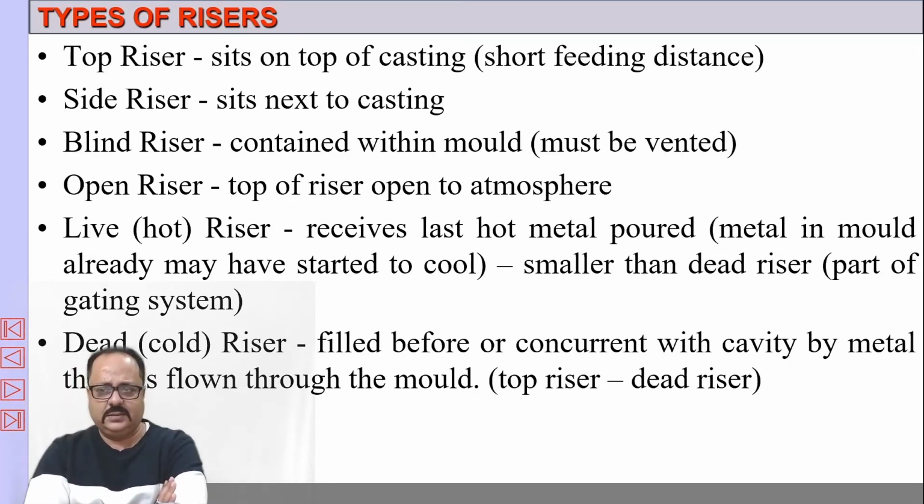Whereas a cold riser is filled before the mold cavity. So the mold cavity is filled through the cold riser. That type of riser is called a cold riser. So depending on where it is placed, whether open or not, whether hot or cold, risers can be named in different ways.